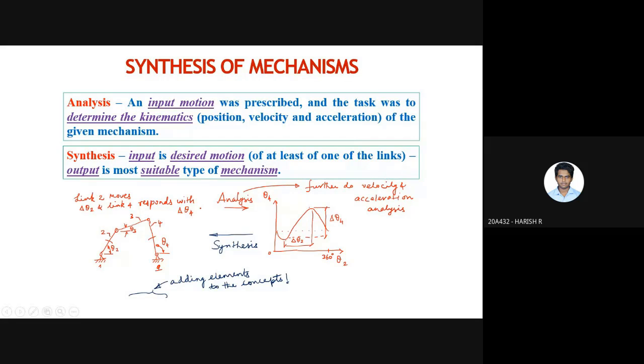Here you look at the diagram which relates analysis and synthesis. Please look at the graph. What is this graph an indication of? Or otherwise, look at the mechanism. What mechanism do you have here, on the left side? It is a 4-bar mechanism consisting of 4 links: the frame, which is mentioned as 1, the crank 2, coupler 3, and rocker 4. And your angles are mentioned here.